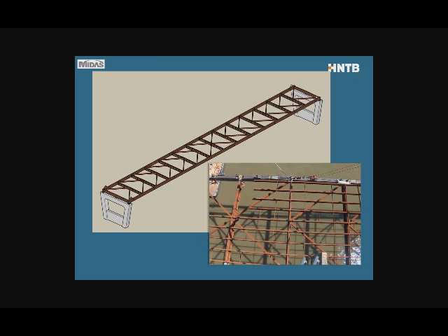Okay, next stage, I've added the bracing. This is the lower lateral bracing, which serves as a deck bracing during construction stages. And in our case, the bridge is very wide, 107 feet center to center of floor beams. And so to prevent lateral torsional buckling of the floor beams, the bracing system actually engages the top flanges of the floor beam and holds them against the lateral torsional buckling.